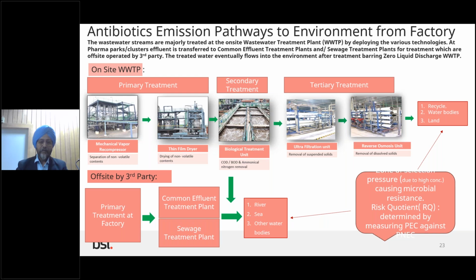So usually it has three treatments. The first one is primary treatment, and the primary treatment actually entails high dissolved solids, the high TDS stream, and it is usually processed, for example, a mechanical vapor recompressor or multi-effect evaporator is applied. Usually all antibiotics which are in dissolved form, as well as the salts, are removed, and usually they are dried in a thin film dryer. Eventually, they find their way to landfill. In the landfill, whatever solid is removed from the thin film dryer is handled as per national legislation. So usually these landfills are leach proof, in order to prevent leaching to the groundwater to avoid AMR as well